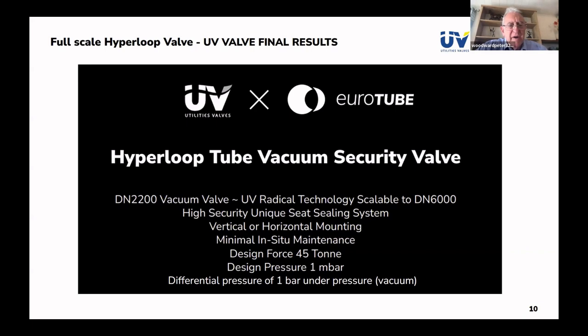It will require that the valve is supported on its bottom edge and guided on the other side of the valve. And we will be looking at how to have a rail system for the valve to slide backwards and forwards on, which is basically wear resistant and doesn't need replacing.